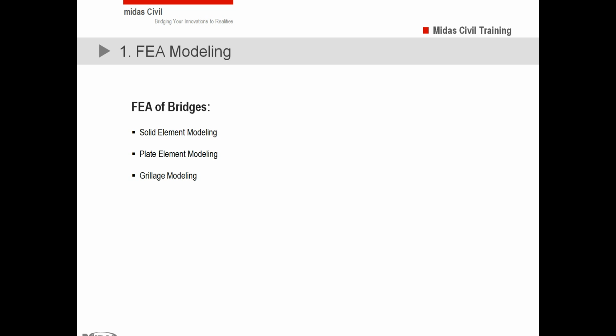They are 3D finite element analysis solid elements. You can also represent the entire bridge using shell elements, and the grillage modeling approach can also be done. So these are 3 different types of modeling approaches that can be applied in any finite element analysis software, including Midas Civil, and the practicality increases as you go from top to down, and accuracy increases if you go from